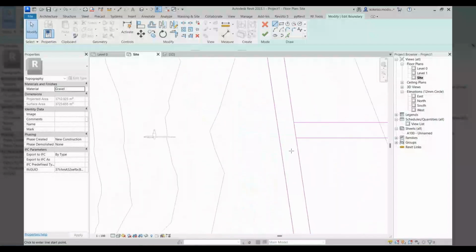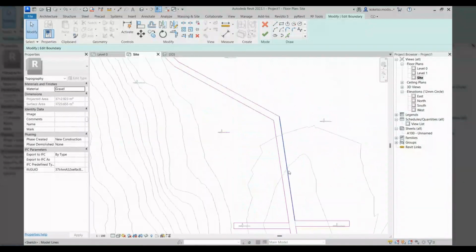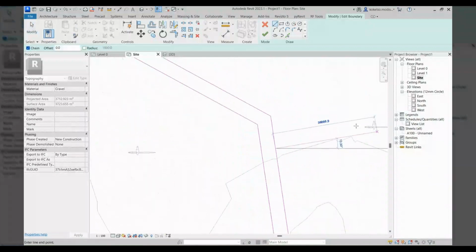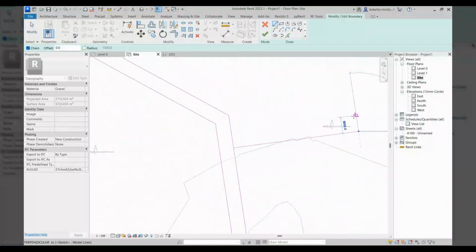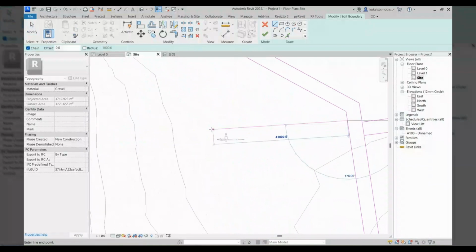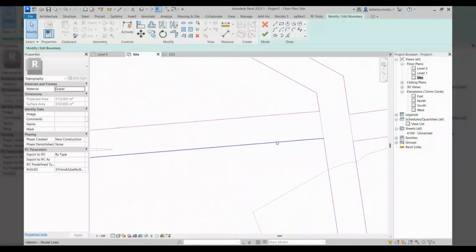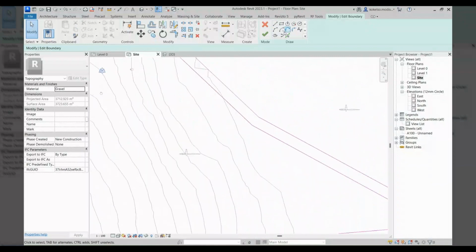And then another one this side. So it's gonna be 5,000. SL for slice. So I'm gonna slice these points. And then I'm gonna remove them. So I'm gonna do the same thing this side. 5,000. Place them like this. 5,000. SL for slice. And then also for these ones.